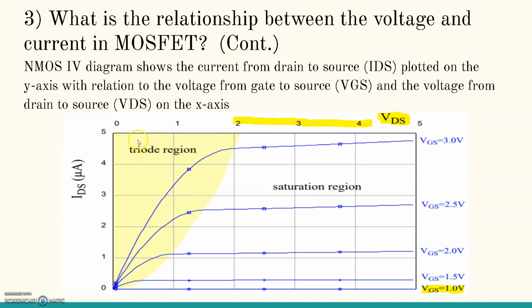So this is just a diagram showing that relationship between the voltage at the gate and the current. As you can see here, when it's below the threshold, there's no current running through. But when it reaches over the threshold, you see the current starts to gradually rise, but it becomes linear, and then it goes to the saturation region.